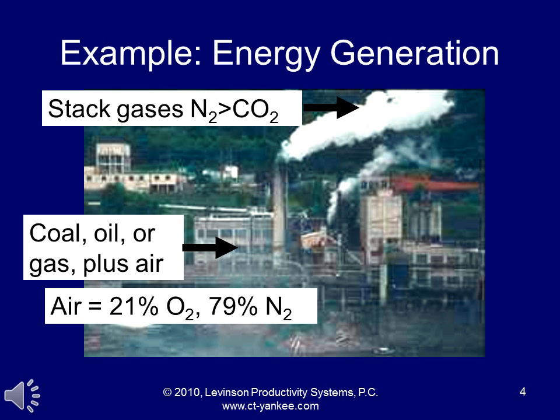Now, if people are fixated on carbon dioxide, they're going to overlook the nitrogen, which is actually carrying a lot more heat up that stack than the carbon dioxide. The nitrogen is carrying the value of your fuel up the stack, and that kind of waste is invisible to a carbon footprint metric, but it's forced to become visible by a material and energy balance.